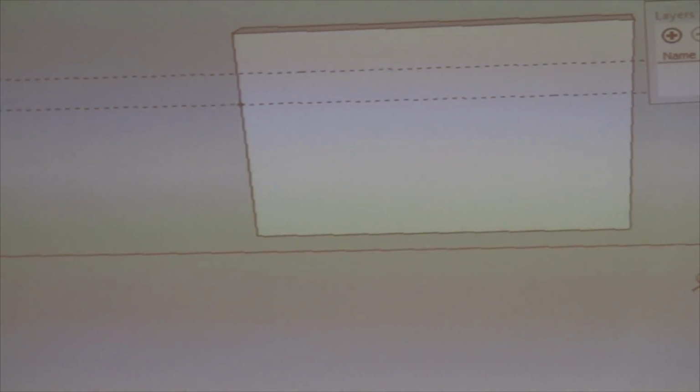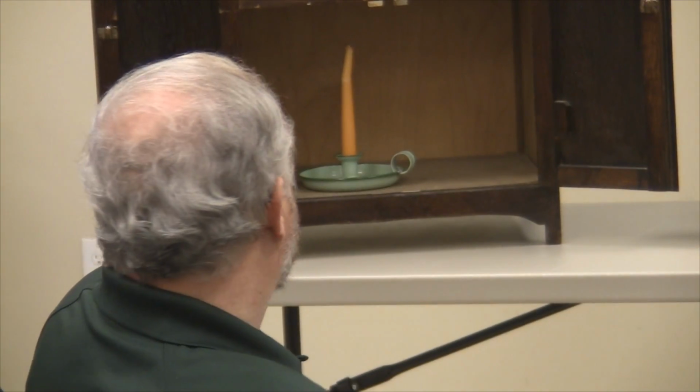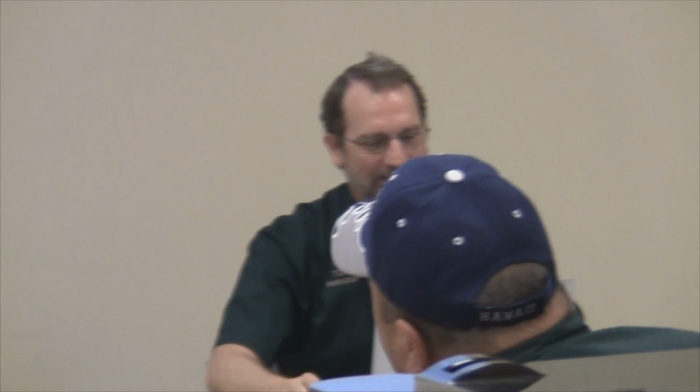Also remember too, on a guideline, you can draw it not on the surface. Be careful, because sometimes, if you're not careful with your mouse, you'll actually pull it off of the surface, and then you've got a guideline, you think it's where it is, and it isn't. Right. I've never done that. I haven't done it since Tuesday night. You get used to it.